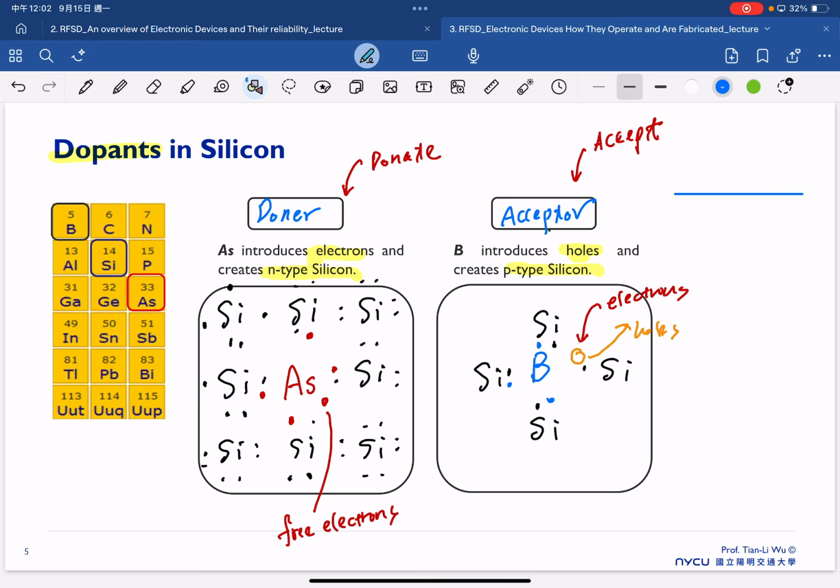In reality, if you consider the structure of the MOSFET here, normally we have N plus in the source and drain, and we have P minus in the substrate, and this plus suggests that we have high doping. But in the semiconductor world, we don't call this high. I don't know why, but we are just used to calling this heavily doping.